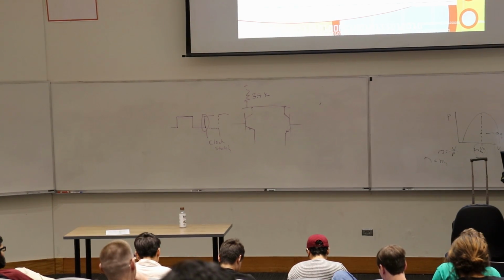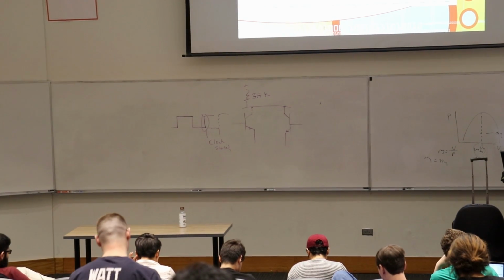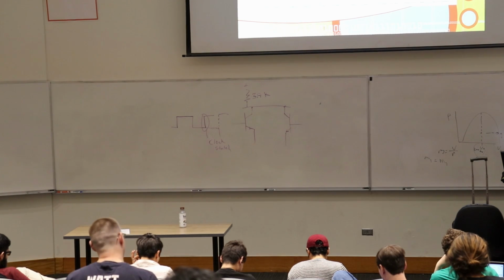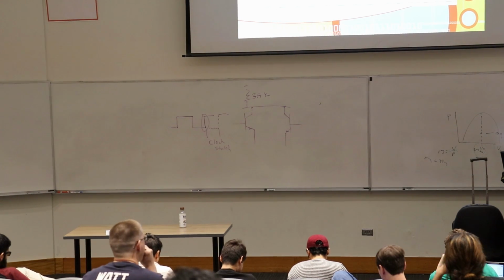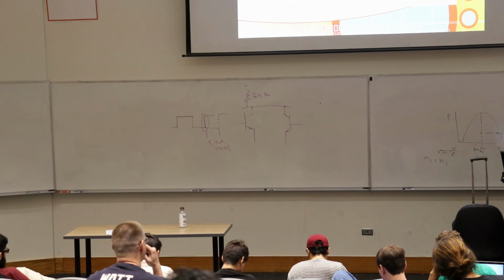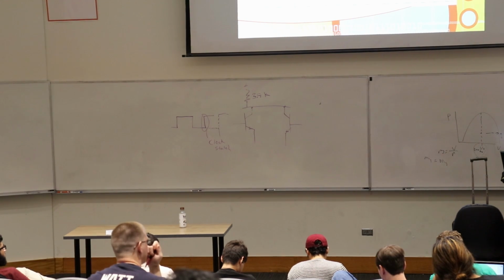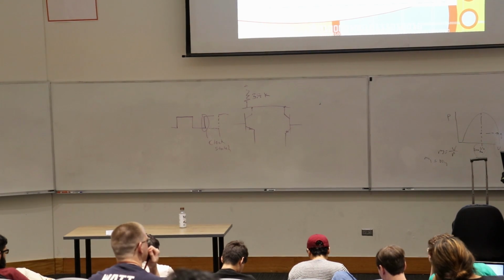But anyway, okay, so that's how this works, and it's pretty cool. And it turns out that this skew in parallel interfaces causes some real problems. And so you can fine-tune a single wire to run a lot faster than you can 8 wires in parallel. That's, I guess, what turns out to be the case. Sort of surprising to me, but that's how it works, and that's why your disk drive in your desktop or your laptop is a serial device. It's not a parallel device.